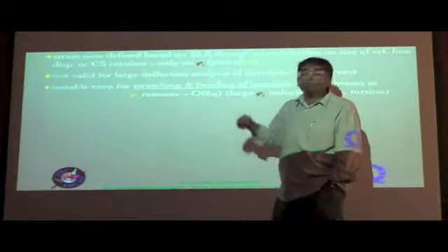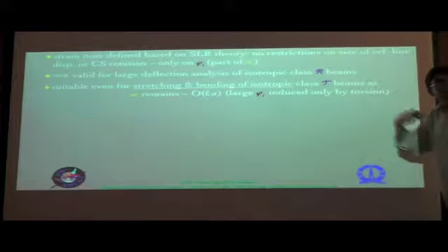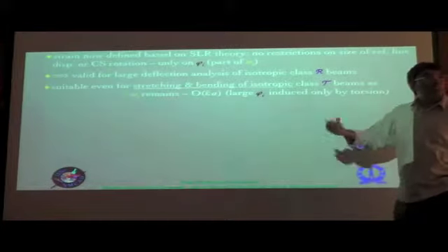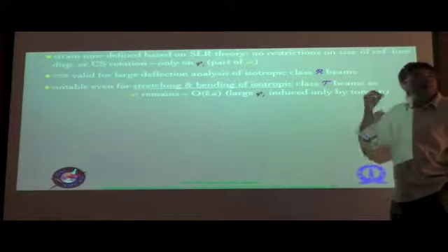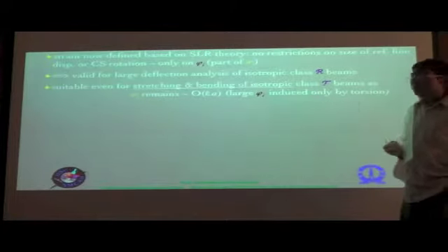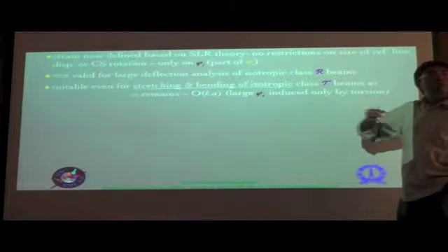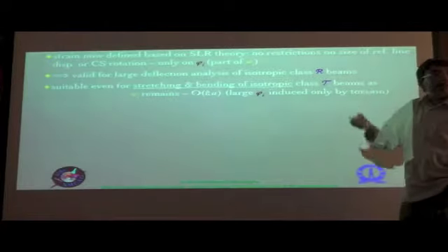The situation becomes a problem only when you have local rotations which are larger, which are of course balanced by some other large terms present in the expressions for the 3D strain, so that the 3D strain itself remains small, but two terms are large in such a way that one is positive, the other is negative in magnitude, and therefore basically you see that the difference is what contributes to the 3D strain, and therefore it is small.